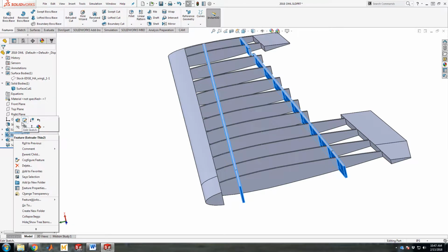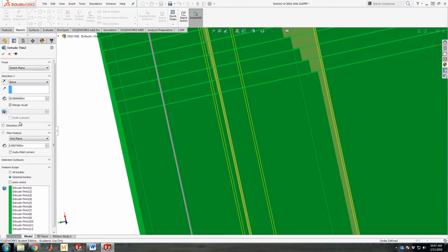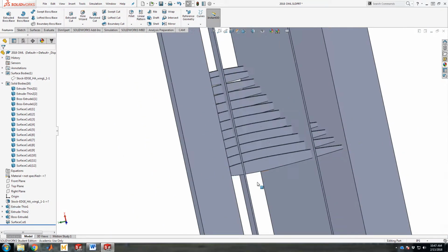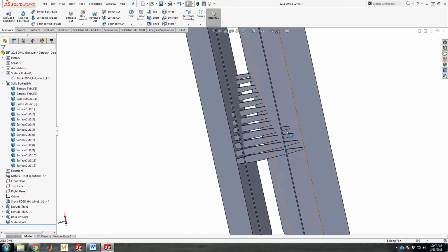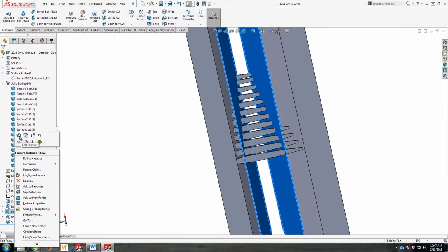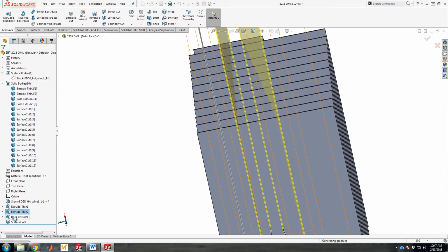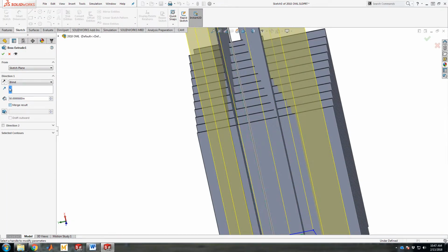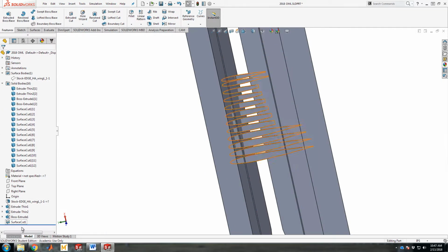So if we go back into the parts, we can now describe how you do multi-body single parts. If you uncheck the merge box there, it should fix the problem, right? Created some other problems. That's okay. We'll fix that too. These need to probably also be unchecked. Oh, it already is. But this last operation, each extrusion will try to merge everything.